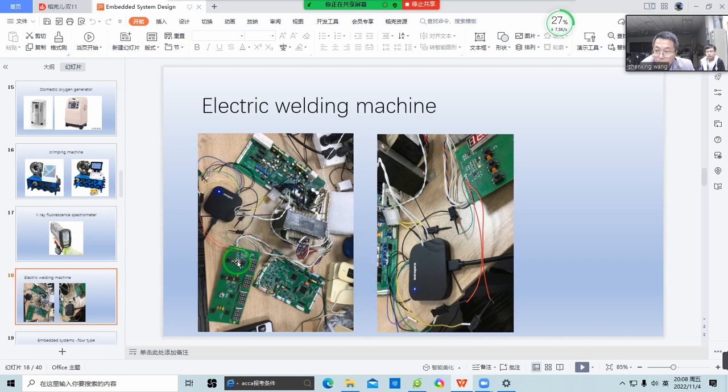So I told him, if you want to replace it, you should take the machine to my office. Then I use this kind of device. This is very important. This is a logic analyzer. I connect the logic analyzer to the serial port of the keyboard and display, analyze the communication signals, and later find the pattern of communication.